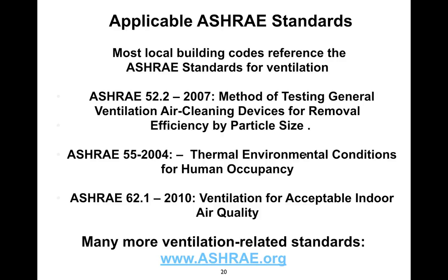ASHRAE, American Society for Heating, Refrigeration, and Air Conditioning Engineers, is an engineering society that has published many standards regarding air conditioning systems and air handling systems in commercial office buildings. There's a few of them that are particularly of interest to us when we're looking at indoor air quality. The first one is filter type devices. 52.2 is for standards for filters on HVAC systems. 55 is for thermal comfort. In other words, what temperatures are acceptable.